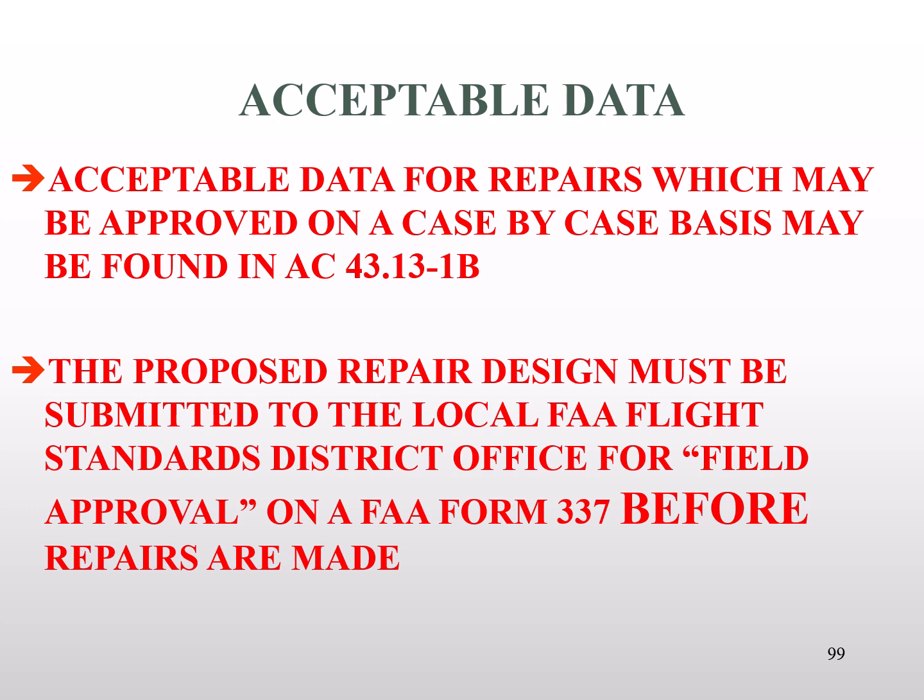Now, never start the work before you have approval, because you may end up with an unairworthy repair because they didn't approve the data and you've already done all this work.